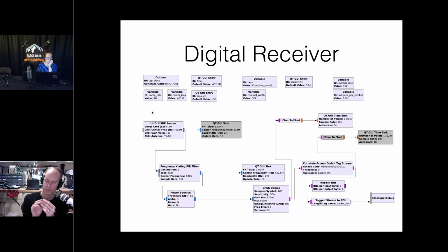But there's something called an SMA connector, which almost all of the SDRs you're going to use have, this SMA connector here. That's the only thing you want to make sure of: you get the right one, and don't get RP SMA. That's this weird thing the FCC made the Wi-Fi people do so that you couldn't swap out antennas easily. So avoid RP SMA unless you have an adapter of some sort, which you probably don't.